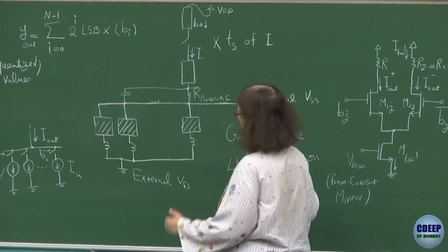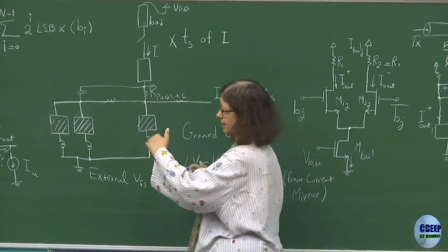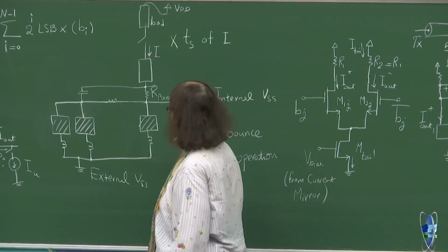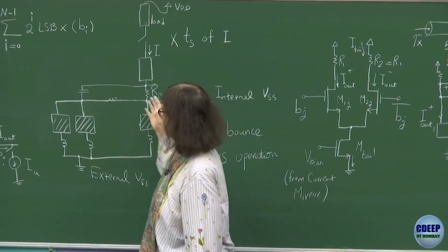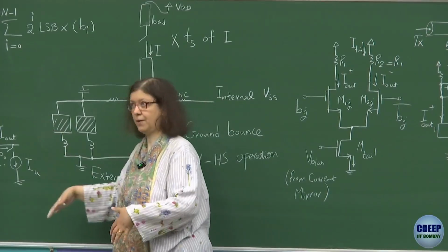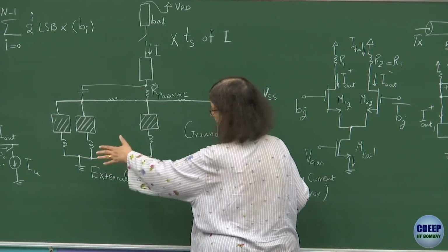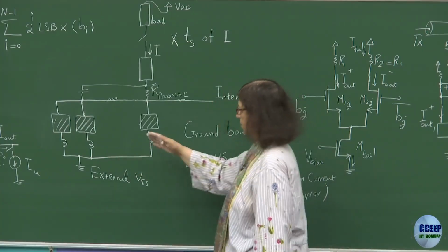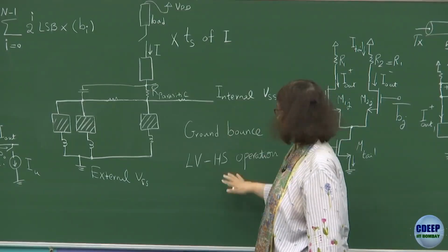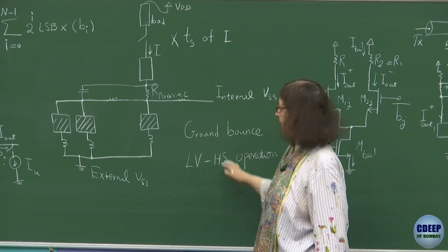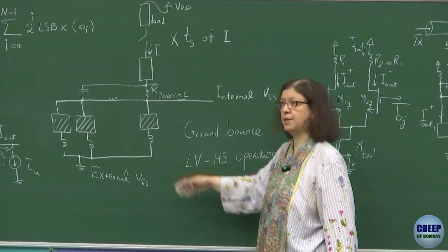And if there is a connection from the top metal sides to that, then you can get a direct connection to the VSS of the board through that connection. That's why these issues will reduce further. On-side, this is on the chip, this is outside the chip, and this is what is sitting between them.